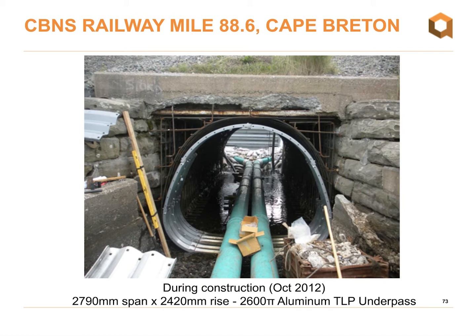The reinforcing steel was again placed between the host structure and the new liner plate, and then the void was injected with a non-shrink flowable grout through factory installed grout boards.